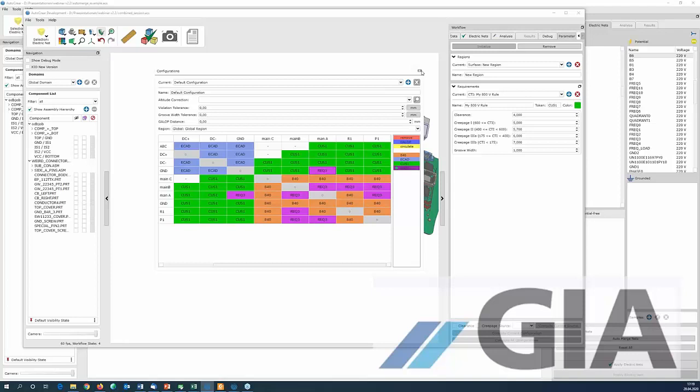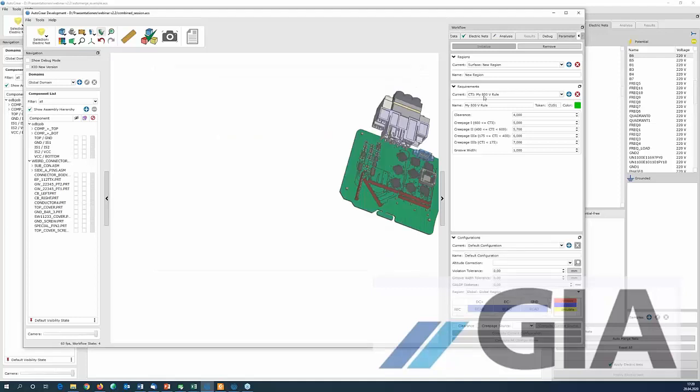And this is also useful if you have only mechanical parts and or assemblies, and the standard table would be a total overkill for you, because you only have 3 different voltage differences appearing in your assemblies, reflecting to 3 different requirements. You just can define certain of these requirements with custom values, defining them, one rule for 800 volt difference, one for 400, and so on.